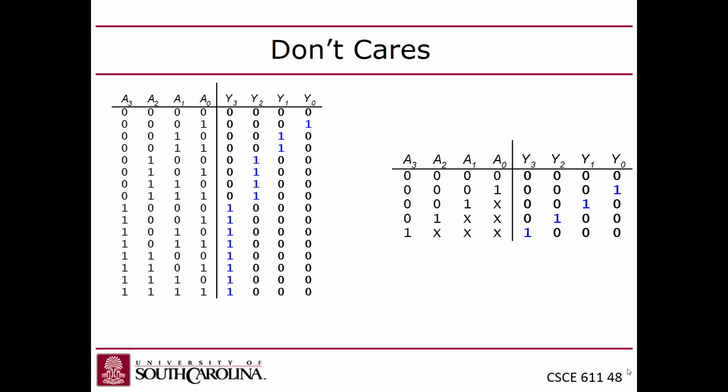Okay, so another thing you can do to simplify a truth table like that is use don't cares. You guys remember you covered don't cares? You might not have covered them like this though. You might have looked at don't cares in 211 for outputs, right? So sometimes you have an output that's a don't care, and if you do, you can use that to help you minimize the circuit. But don't get confused here. These are don't cares that are on the inputs. This is a little different.